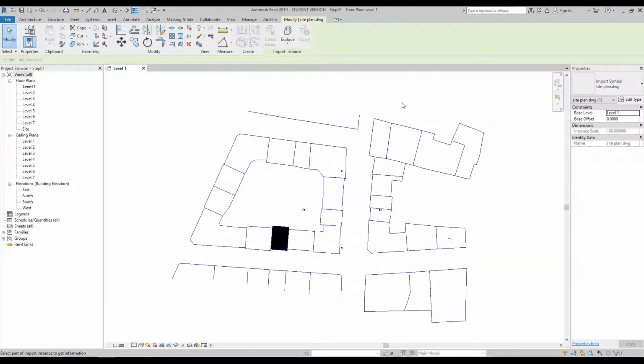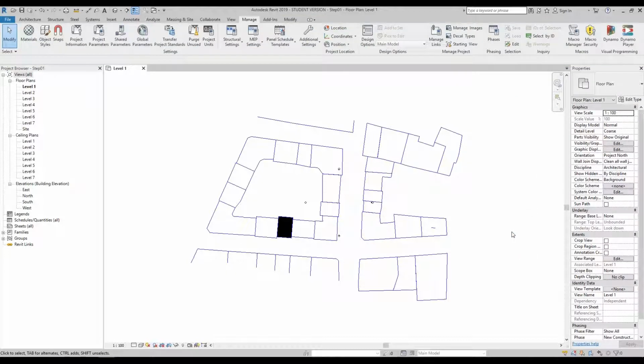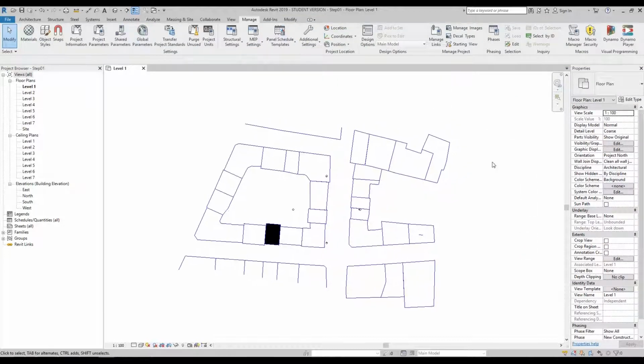Now, once you've done that, it is important to know that under the query tool, if you press in negative space, it does not finish the command. So to do that, you need to press escape twice, and you will go back to your normal user interface.